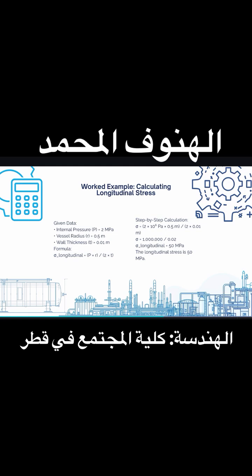Example calculation: longitudinal stress. Given data: internal pressure is 2 megapascals, radius is 0.5 meters, wall thickness is 0.01 meters. The result is a longitudinal stress of 50 megapascals.